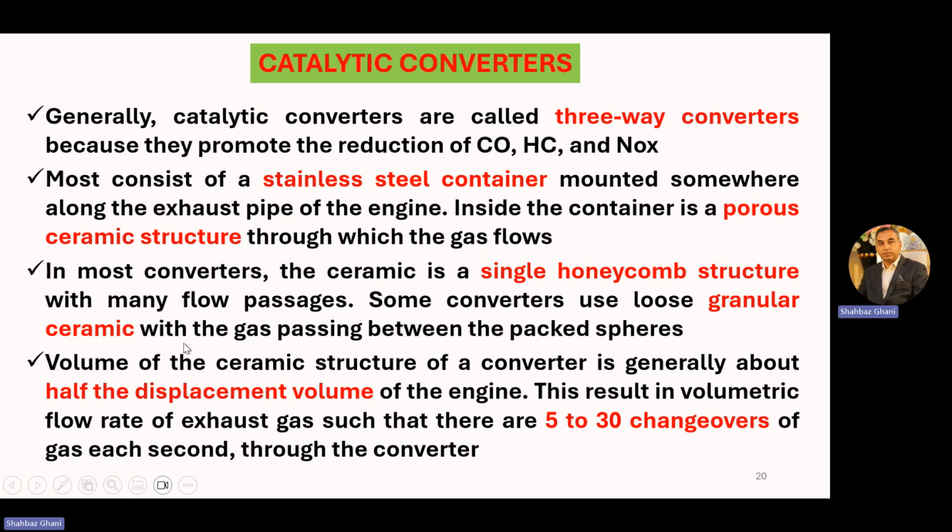The volume of the ceramic structure of the converter is generally about half the displacement volume of the engine. So this is very important: the ceramic structure, not the whole converter. This results in a volumetric flow rate of the exhaust gas such that there will be 5 to 30 changeovers of the gas each second through the converter.